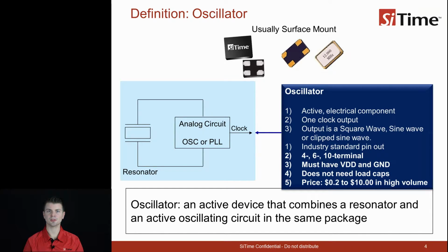By contrast with crystals, the system designer must consult both the crystal's datasheet and the datasheet for the IC containing the oscillator to ensure they will work together under all conditions. Therefore, with the crystal, responsibility for guaranteeing proper startup falls on the system or board designer. With oscillators, responsibility for guaranteeing proper startup and operation rests on the oscillator manufacturer.